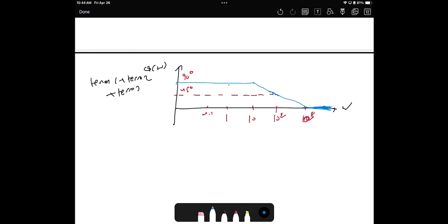The other thing, as you will discuss later in control systems, is how fast the response is, which is based on the location of the poles. Roughly, as an example, the farther you go into the left-hand side, the faster the system will be. If you go closer to the imaginary axis, the system response will be slow. Then you will have some challenges. Okay, I need to make the system fast, but I have physical constraints. I cannot make it super fast. At the same time, I don't want to make it too slow. So you need to get the optimal performance.